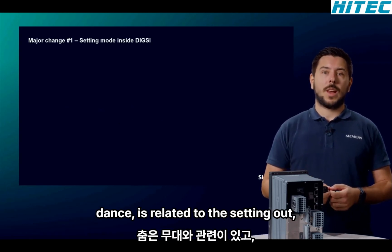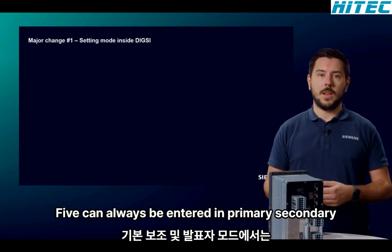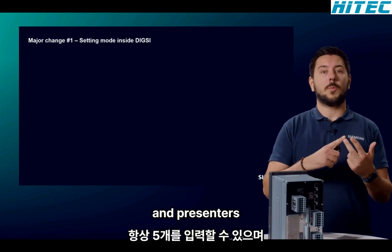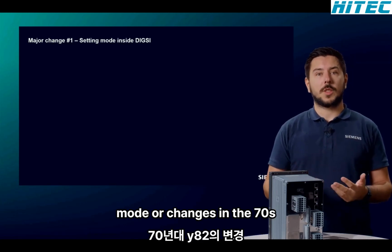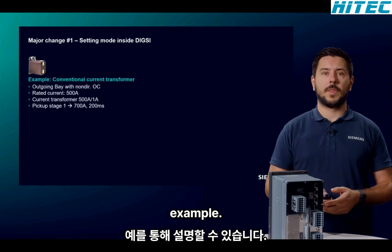The first change is related to the setting mode. The protection parameters in DIGSI 5 can always be entered in primary, secondary, and percentage mode. What changes in the 7SY82 can be explained with a short example.